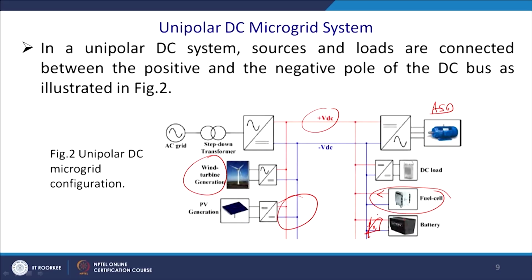You can see that a simple diode can operate, because charge can flow this way, and once it is on, you can turn on the mechanical switch for charging, and for discharging you can take a different path. But in general, to control it actively we require to put a bidirectional DC to DC converter in front of the battery.